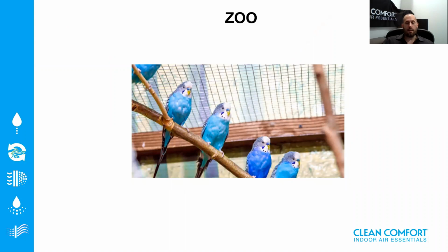Zoos. Now, the first thing to note is that zoos can be harder to deal with than hospitals. They care deeply for those animals. Now, normally we get calls to work in the bird area or the reptile area, and it's usually that they want to reduce the odor. So the solution is more fresh air, add filters, and add purifiers. Now, one note, reptiles absorb moisture through their body. So you have to be extra careful when you're dealing with reptiles.